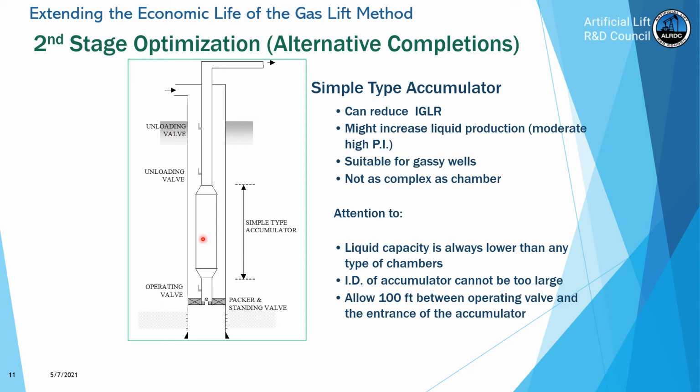And the other thing is that we're going to generate a large liquid column here, and we also need to make sure that the pressure is high enough and the gas flow rate is high enough so that the liquid slug will travel at a high velocity.